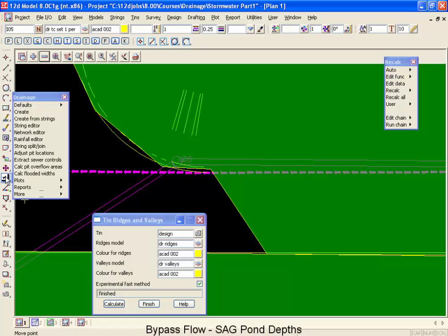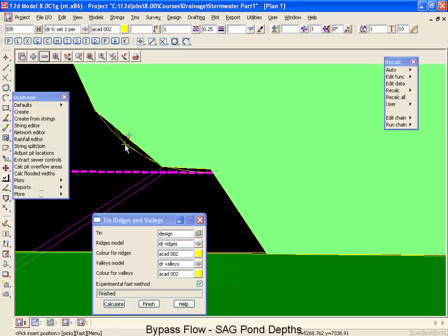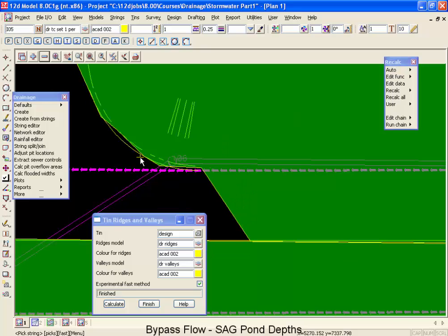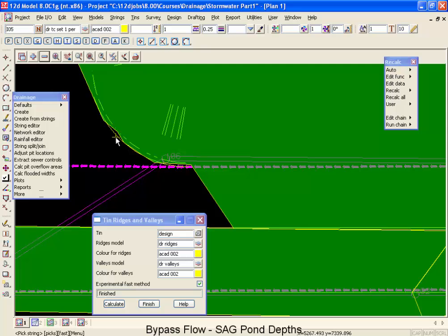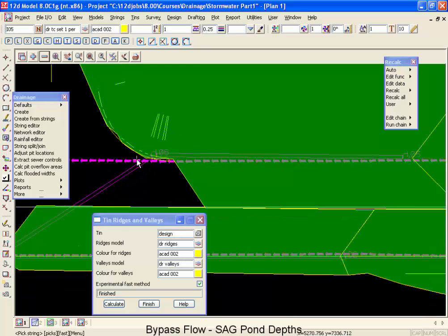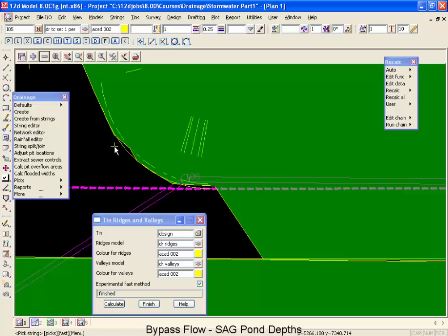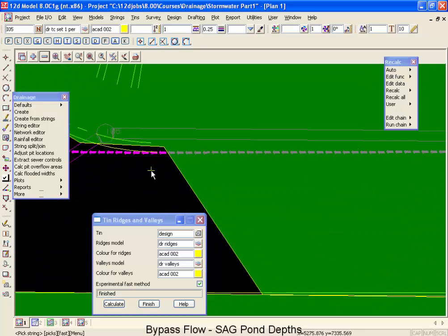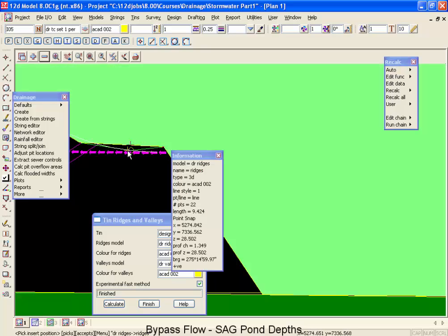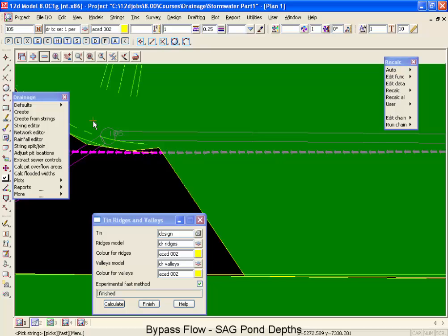I'm going to come across to our vertex, drag this all the way across to the insert mode. So I'm going to select my catchment vertex, come out and bring this out just a little bit closer to that ridge line, snap on there. And I'm going to do that again for here, bring that out and snap onto there. And I think I need to move that point. Let's check out here. This is looking pretty good for around there. Cutting across. Looks like I'm a little bit out on here. I'm going to insert a new point for here, and then I'm going to come back and move this one.